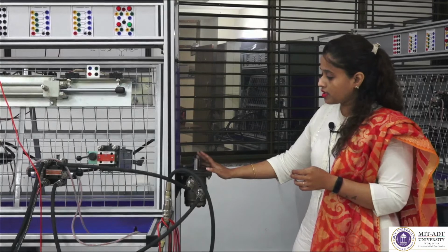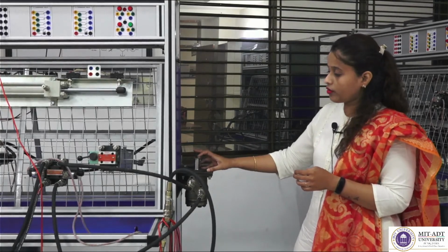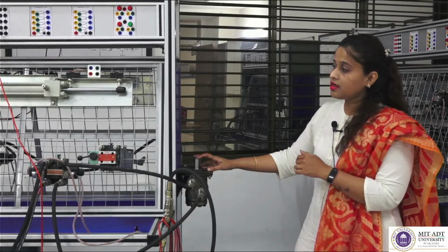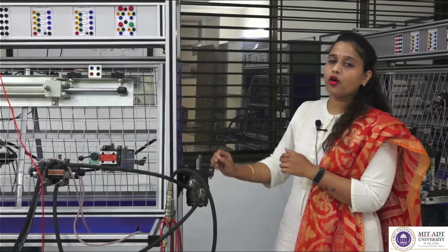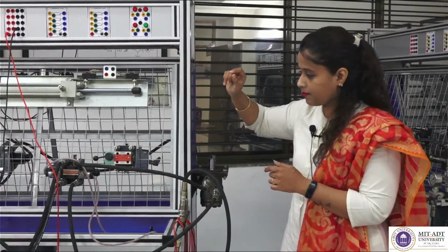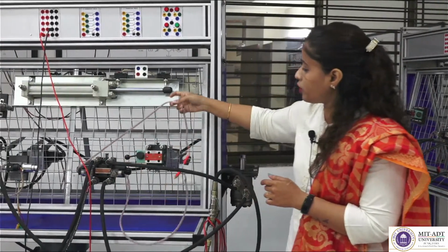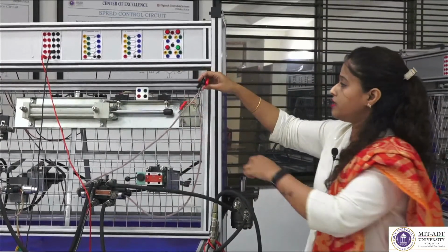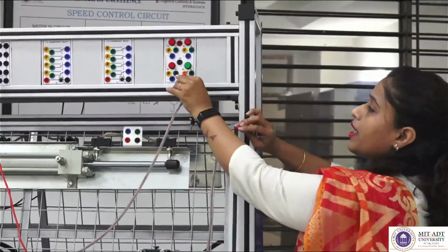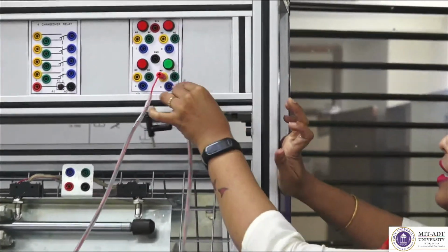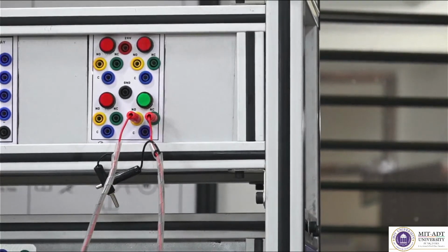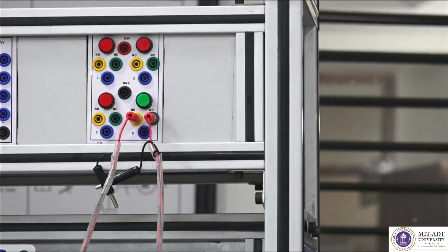So, quickly see how the shaft is going to rotate, whether it is going to rotate clockwise or anti-clockwise, depending upon the both side operated solenoid valve with the help of some electro-hydraulic system. So, same connections I am going to place for push buttons. Just give me a second. All red color wires into NO and NC. All black color wires need to be grounded up with the ground signal taken from here.